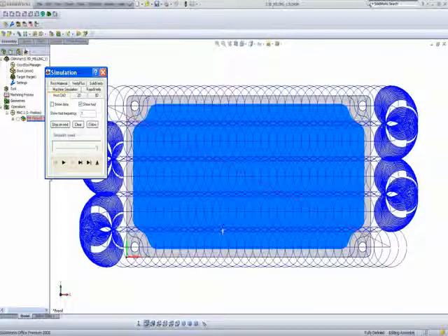There's a 5% overlap between the tool paths, and the tool leaves the part itself, because I wrote down 110%. If I would have done 50%, then the center of the tool would have gone over here only.